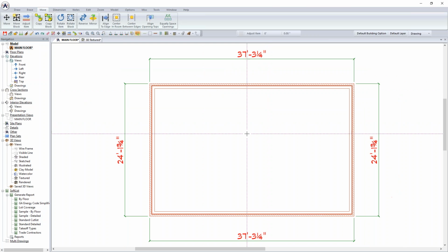When you click zoom extent, it will blow your drawing up to the largest possible zoom scale on the screen, including dimensions and all of the objects, notes and so on, so that you can see it. So as soon as I do this, it's going to zoom me out so that I can see everything on the plan. Now, going in and editing dimensions is kind of the next logical step when you're laying a plan out. Let's get the overall footprint set, right?